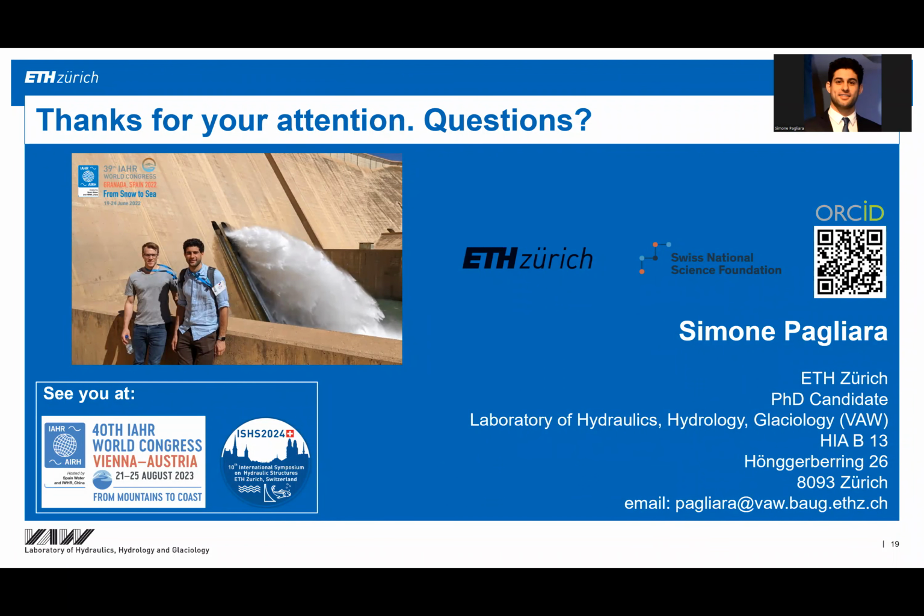Now, since you are forcing the air boundary layer towards the wall, I wonder if you are also modulating the stress on the wall below, which would, in the end, also affect the cavitation, because you are inducing air in the system with very big bubbles relative to the height of the channel.